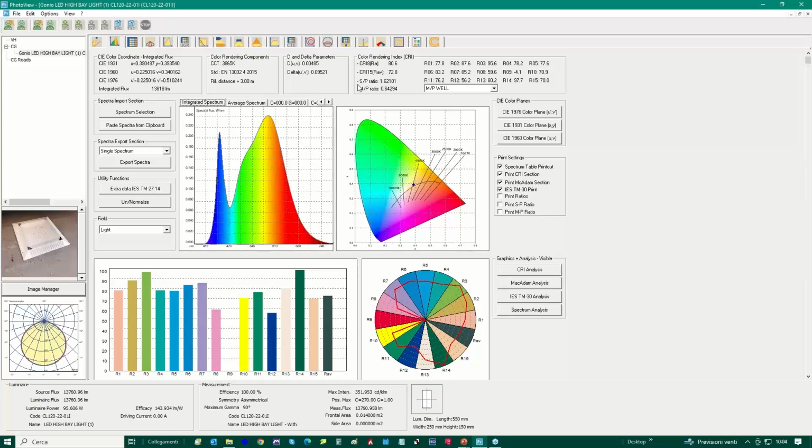If you want to run a calculation, let's say for example, for road lighting, considering that we are during the night and the vision is different, from photopic we go to scotopic, and this is the value 162 that you should apply in order to switch from photopic to scotopic. Again, the melanopic ratio over here in function of the standard you can select over here.